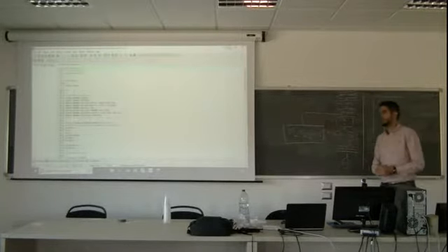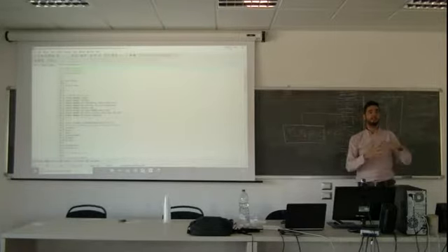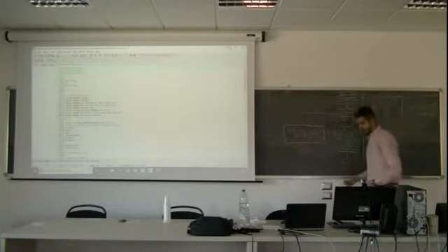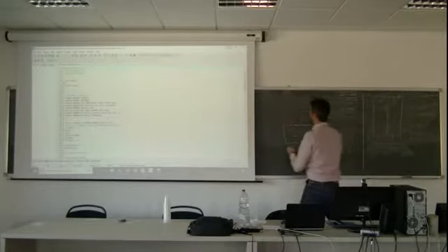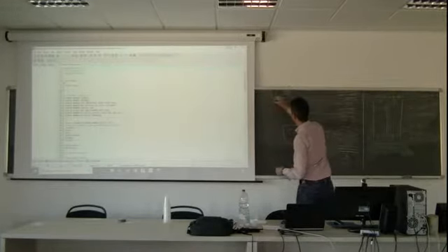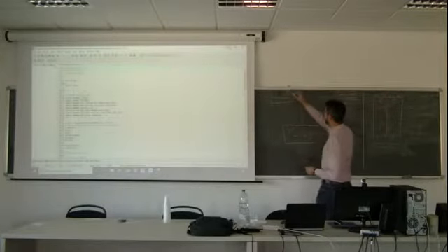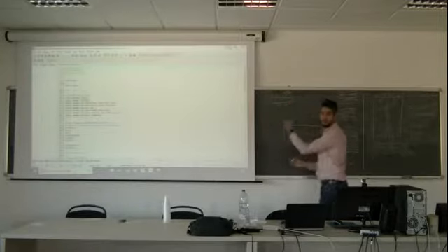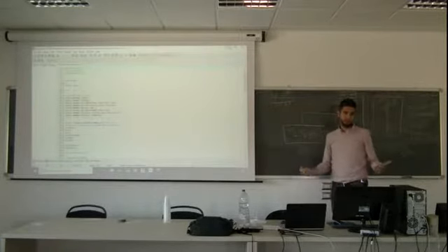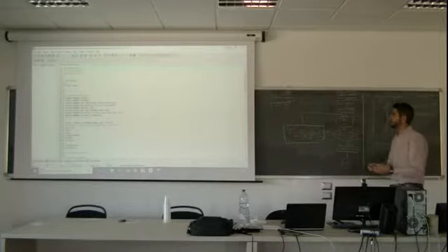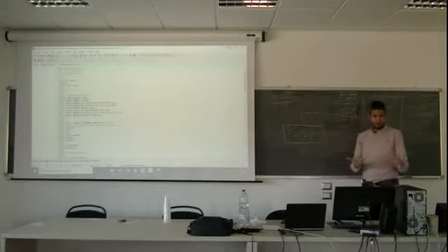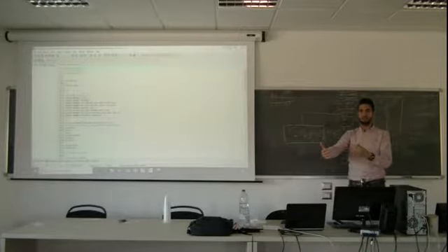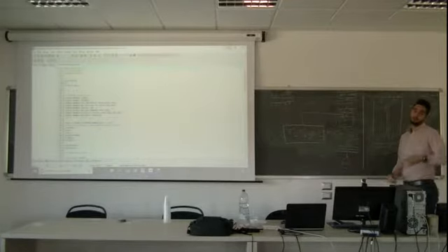Final calculations means computing the amount of heat dissipated by convection, because now I have the real distribution of temperature inside my fin. I know the temperature of air. I can know all the convection that has been dissipated to the outside. So I know how effective my fin is. Right? This is the final calculation. At the end, usually the map of temperature is what you need, but you need to compute something else after you have the map of temperature. Okay? So this final calculation and then end. We can go for dinner.